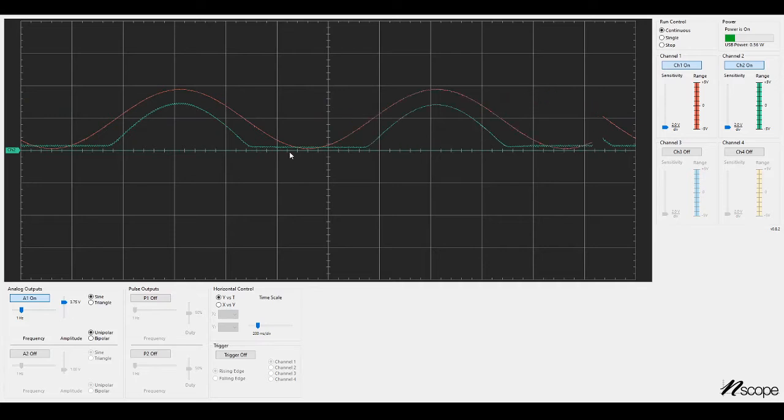When the red line is below something like 1.8 volts, the green line is probably flat, and that's because when the LED doesn't have at least 1.8 volts, no current will go through it, so no light. So no extra light hits the phototransistor. As soon as the red goes above 1.8 volts, light will come out, and that's what hits the phototransistor and makes that go up. Okay, so that's pretty cool.